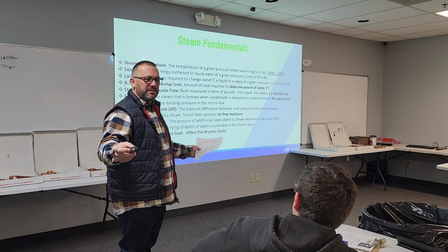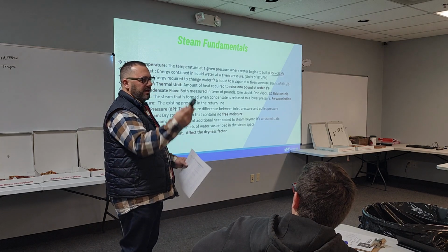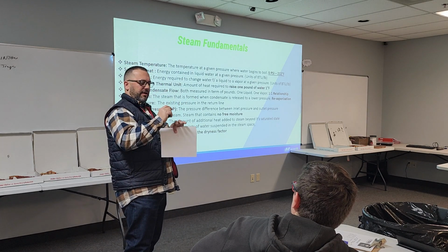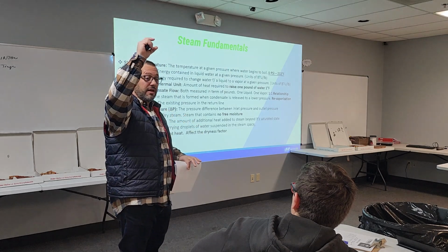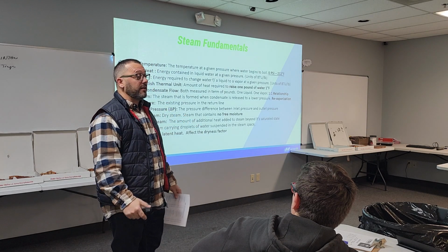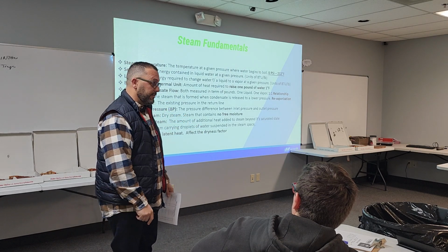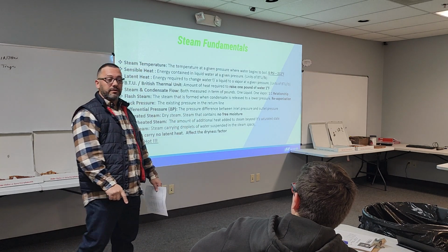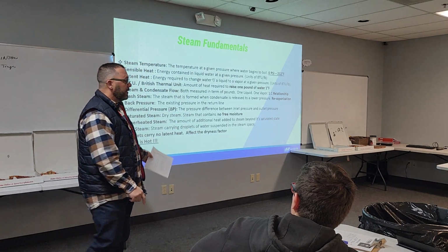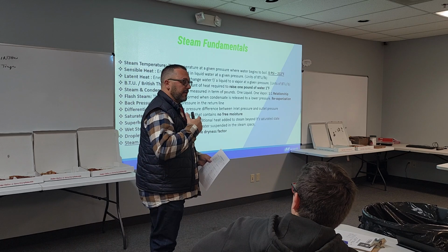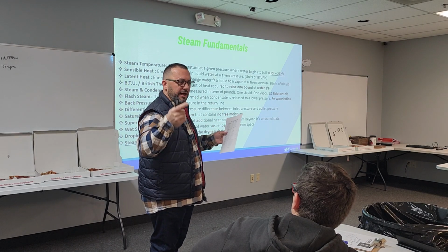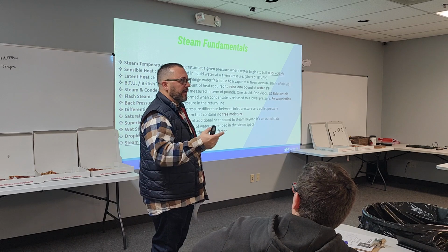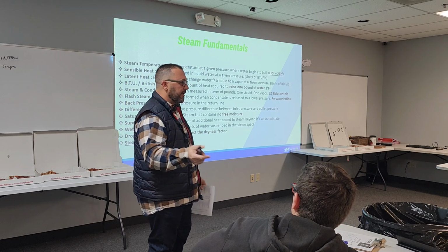That's generally flash steam. When we see plants that have the first half inch of it be clear with a lot of velocity, we know that plant's blowing a lot of live steam through, and there's an opportunity for me. They're wasting a lot of steam. Flash sometimes accidentally gets blamed on traps. There'll be a little bit of flash around a trap, and people might think a trap is blowing by, but in many cases it's not.